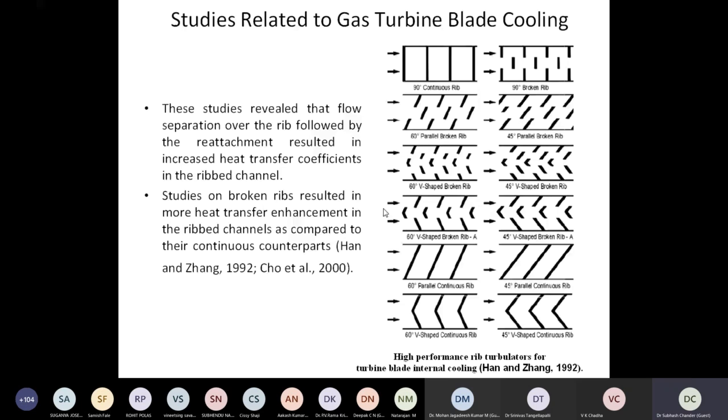But we cannot go beyond a certain very high temperature, because if the temperature goes beyond say 2100 Kelvin or even more, those gases are going to enter the turbine rotor or turbine blades, which are rotating at very high velocity, very high RPM, right? So they are subjected to centrifugal stresses, and the temperature is high, and that can ultimately lead to creep failure, deformation of the blades.